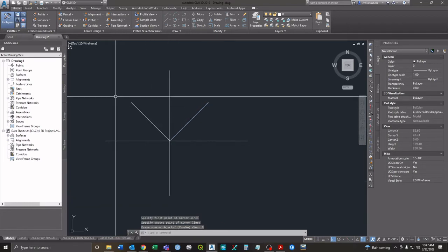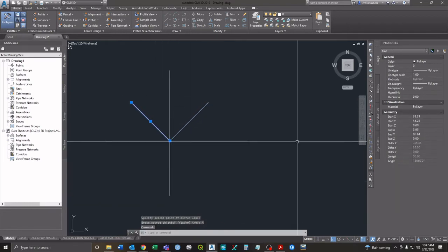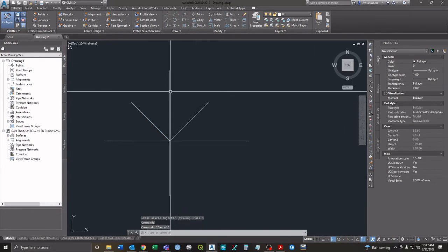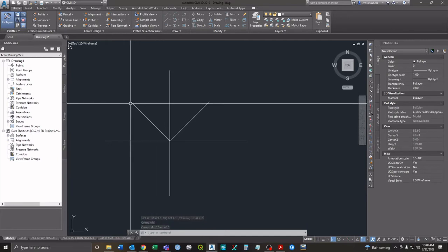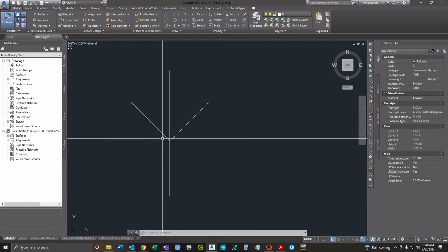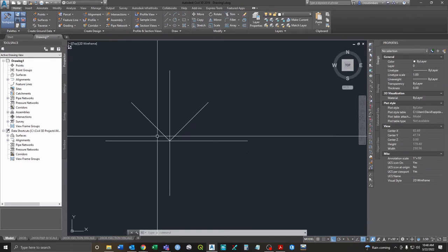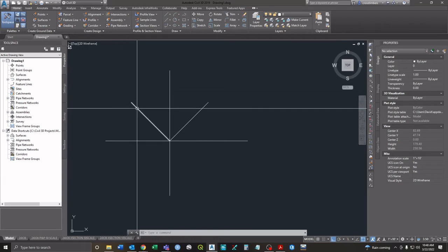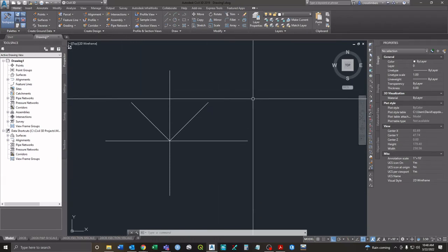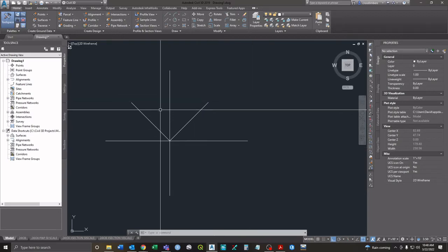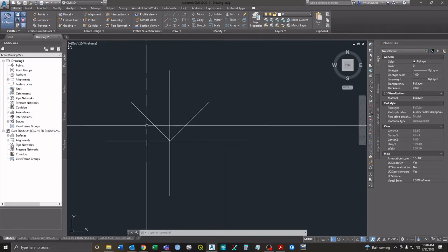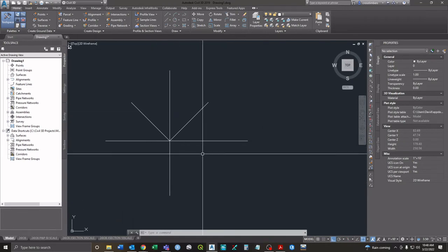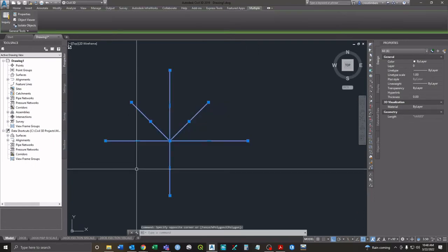I basically just mirrored this over here. Now it's telling me the angle is 135 because we went 45, 90, 135. But in a bearing, it would be 45 degrees, but now it's north 45 west. Does that make sense? Some of this I'm sure you're probably familiar with. So that's how we're going, and this would be south, southwest, southeast, all that stuff.